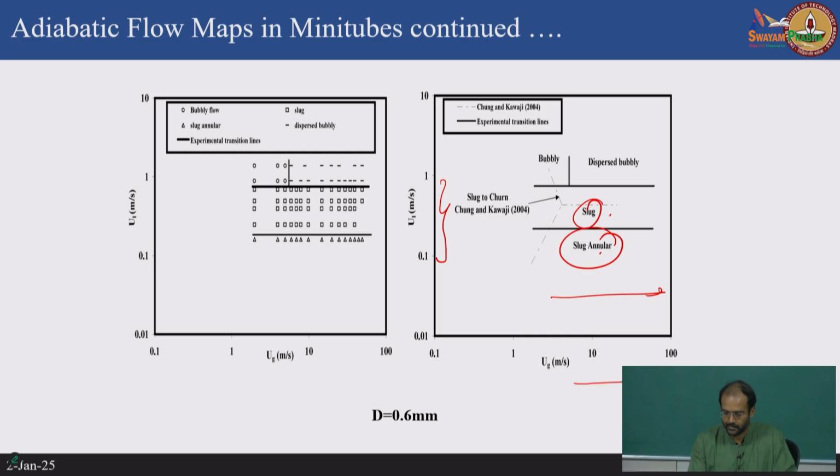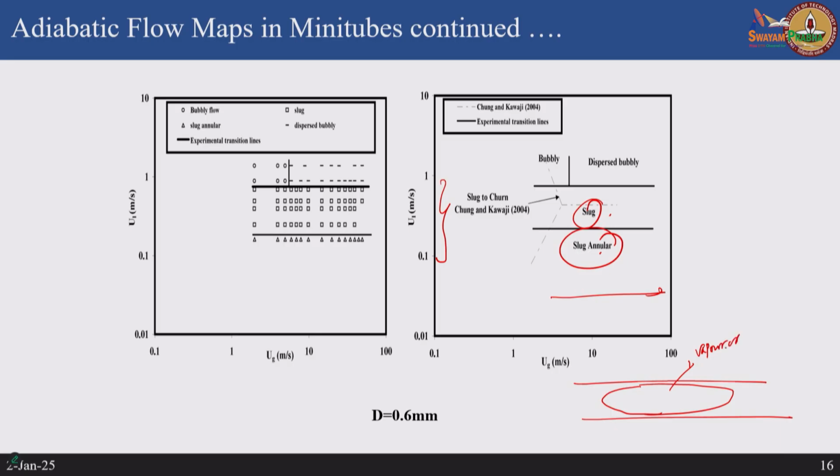The reason being, if you take this tube and you have a slug flow like this, so this is your bubble, vapor or air bubble, and this is your liquid film which is in the annular region, right. So, this is called the slug flow here. If this now grows to a point where the entire liquid core is vapor and only in the annular region I have liquid, so this becomes a pure annular flow.